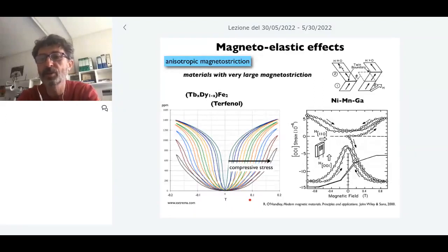It's a special kind of crystal that exists not only magnetic, for example nickel titanium, that exists as an alloy with three elements generally, and they are cubic in one phase, and when they change phase, they become tetragonal. So these are the Heusler alloys. Certain Heusler alloys present this austenitic-martensitic phase transition. So the austenite is cubic, but the martensite is tetragonal.